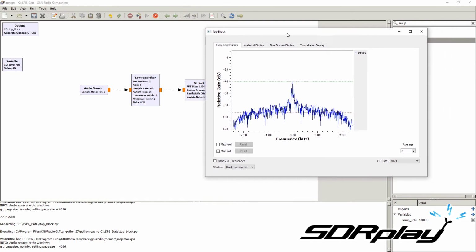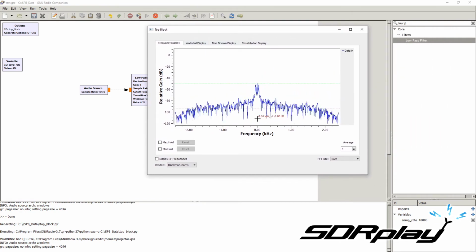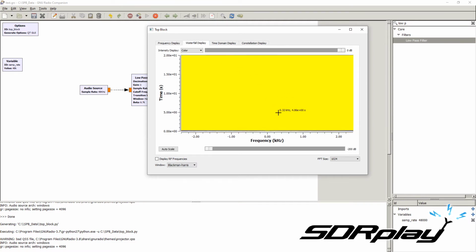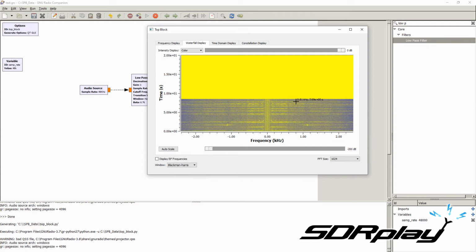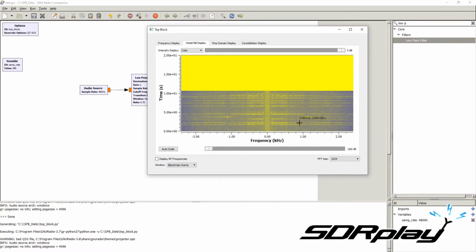And we see now that the bandwidth goes up to 2.4 kilohertz. And all the white space above 2.4 kilohertz is not wasted anymore. Now the whistle, you see, it is more clear. It is 1 kilohertz. And we could isolate it even more.